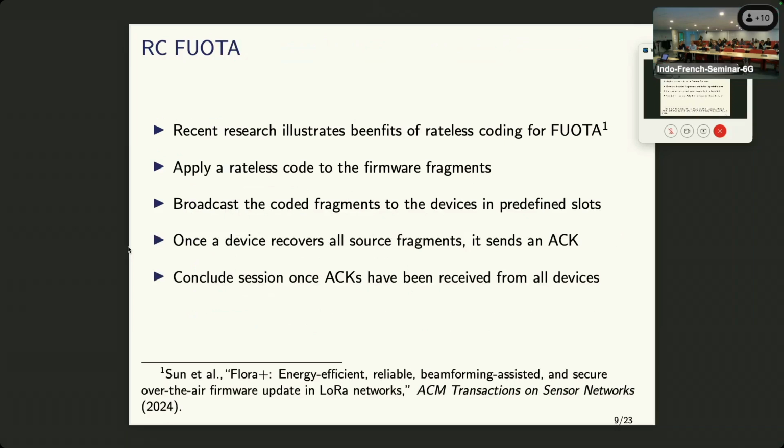Now, in the research community, very recently, there was a proposal saying that rather than using the fixed rate LDPC code, it is better to use a rateless code for reliability purposes. Despite the rateless code's higher computational complexity, the benefit is that if I have a fixed rate LDPC code, once I run out of all the redundancy, the far enough devices may or may not be able to decode the entire upgrade. Most of the time, there are some devices which are very, very disadvantaged, very far away. They get a lot of erasures. Such devices will need an LDPC code of a very, very low rate.